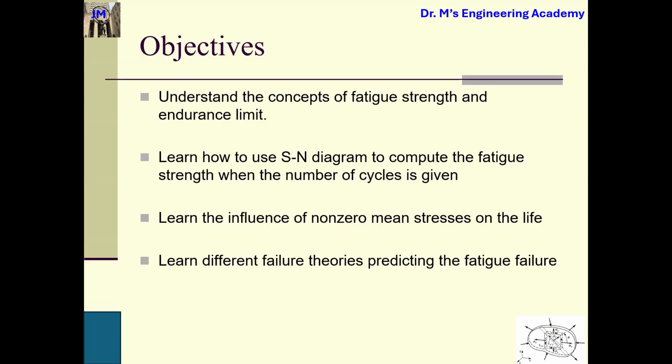And use this S-N diagram to compute the fatigue strength when the number of cycles is given. We also want to learn the influence of non-zero mean stress on the fatigue failure, and then we learn different failure theories for predicting the fatigue failure. So fatigue is very, very important. It is much more dangerous than static loading.